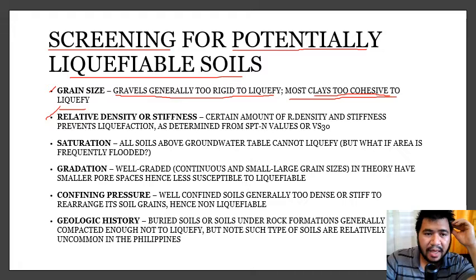You also have your relative density or your stiffness. Relative density is applied for your granular soils, while stiffness is applied for your fine soils like clays and silts.